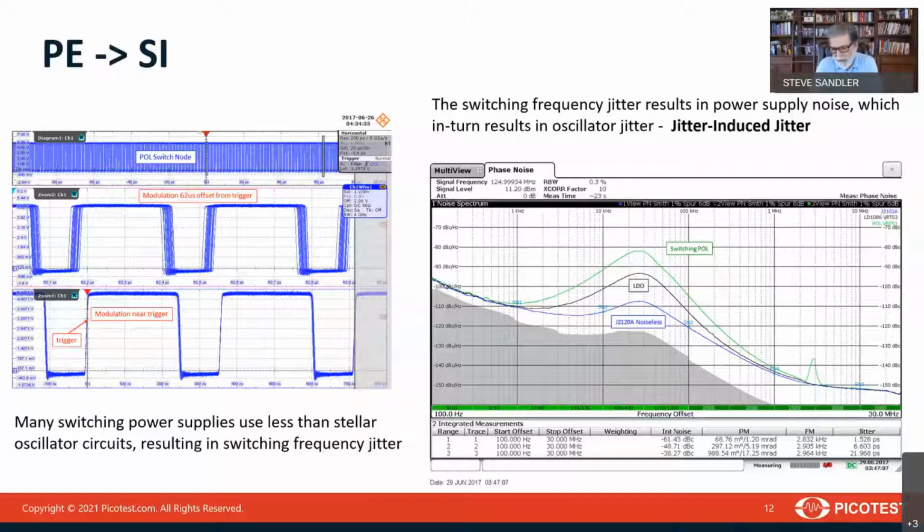And finally, we can power this from an external power supply, so we got as close to noise-free as we could. We used our J2120 line injector, which has about 2 nanovolts per root hertz of noise, and you get the blue trace. You can see the phase noise gets all the way down to 1.5 picoseconds now, but it still has a peak at about 20 kilohertz.